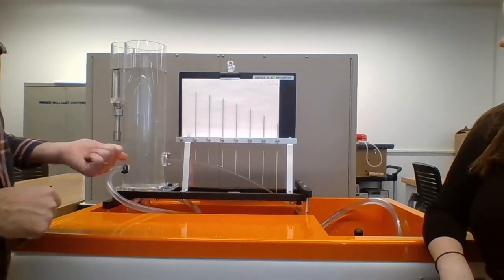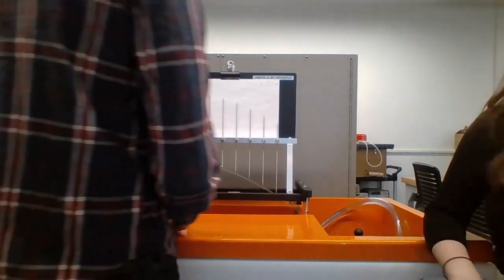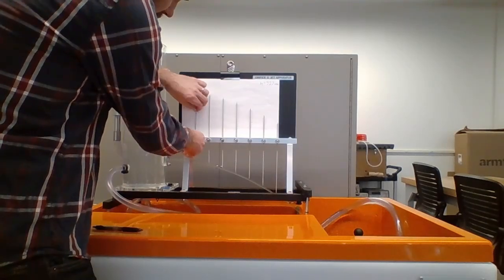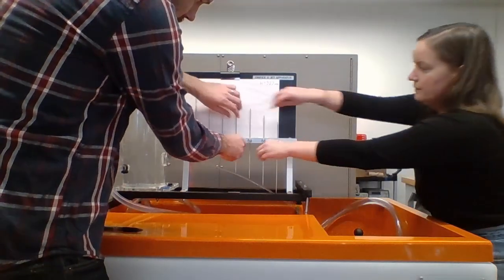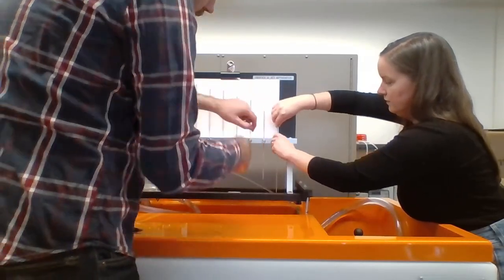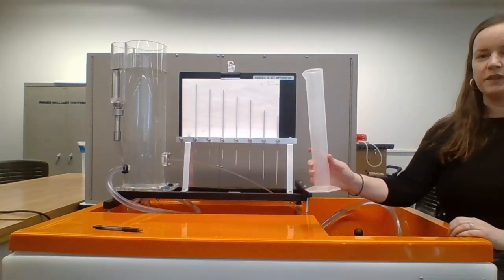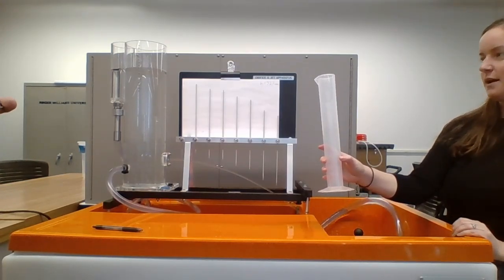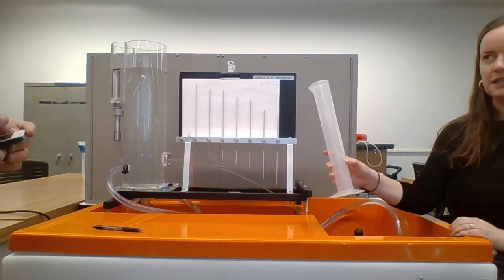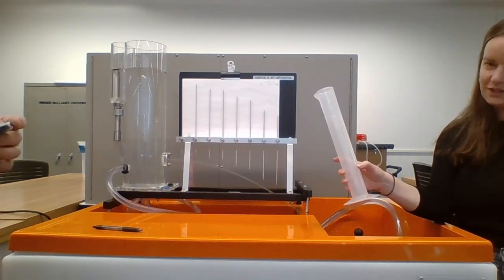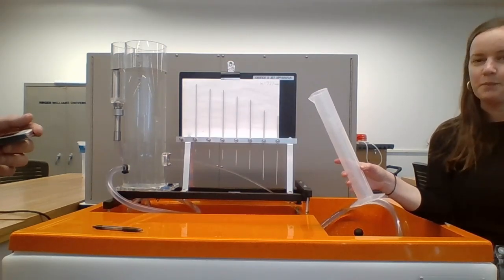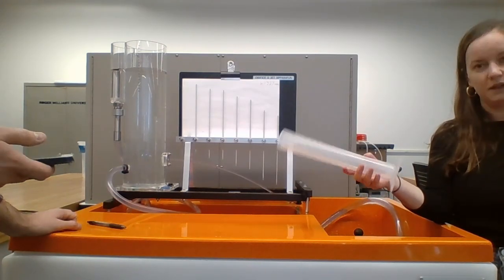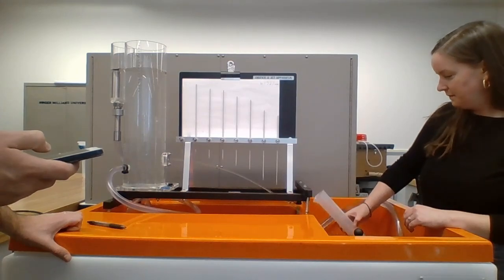Yeah, and now we also have to get a flow rate for this one. So it's a good idea to get the needles totally out of the way so that there's no chance that they're in the flow. So now I'm going to come in with this flask here, and I'm going to use it to measure how much volume this orifice can actually fill. Meanwhile, my trusty lab assistant slash co-instructor slash spouse is going to come up with his timer on his phone so we can time how long it takes to fill a certain volume, allowing us to then calculate a flow rate. Ready? Yep. Steady, go.